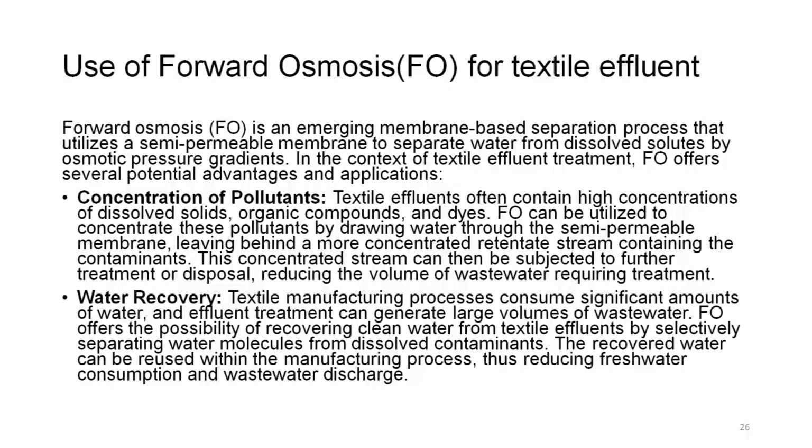Water recovery. Textile manufacturing processes consume significant amounts of water, and effluent treatment can generate large volumes of wastewater. FO offers the possibility of recovering clean water from the textile effluent by selectively separating water molecules from dissolved contaminants. The recovered water can be reused within the manufacturing process, thus reducing the need for fresh water consumption and wastewater discharge.